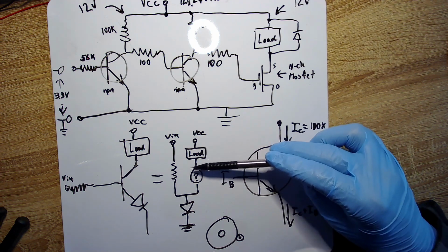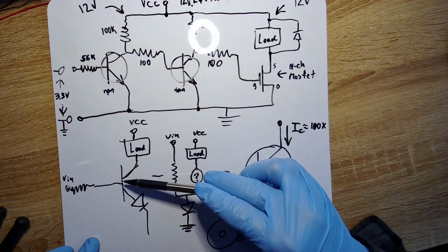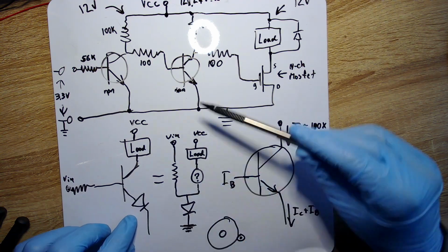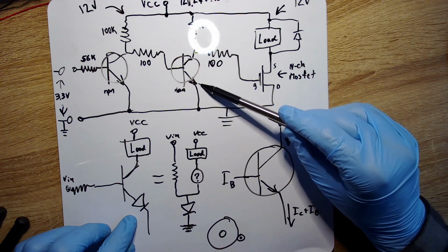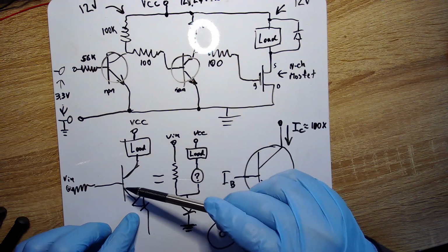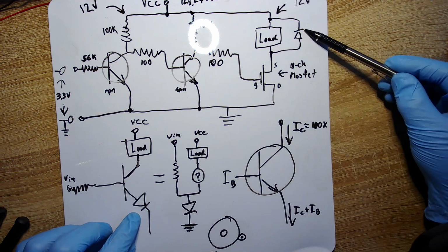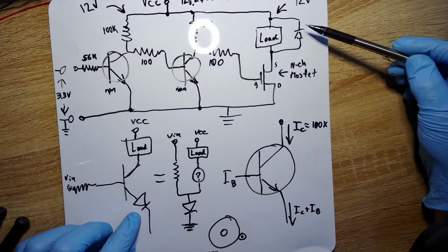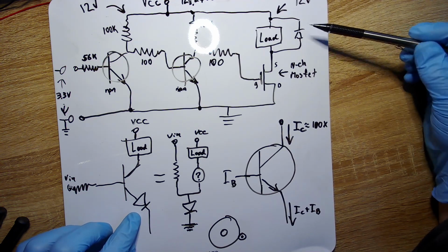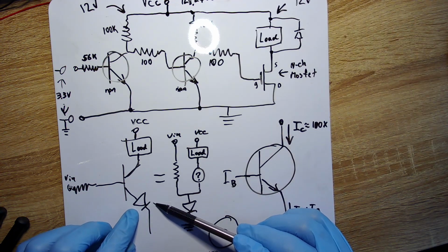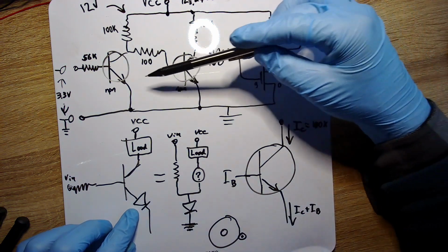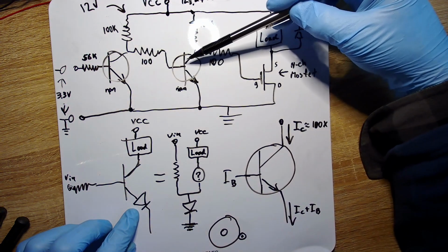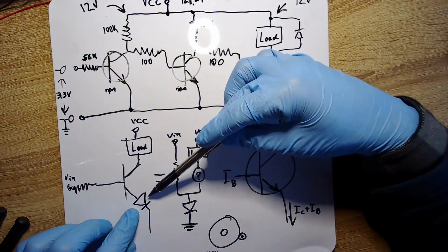If you look at this picture here, this is basically an NPN transistor, where the input basically has a built-in diode, but the diode is in the direction of the flow. So it's not like this diode up here, which is in the opposite direction and under normal conditions is just an open circuit. Here you're going to get your 0.7 volts or whatever. So yes, at every NPN transistor you have to overcome 0.7 volts here before this thing starts turning on, because there's a built-in diode right there.